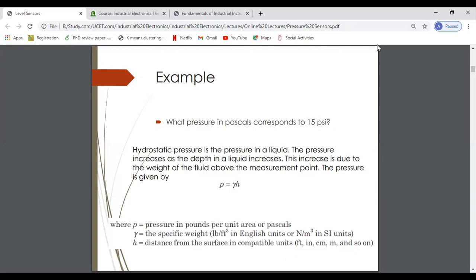As we have seen, it is not a very convenient unit and is often used in conjunction with the SI standard prefixes, for example kilopascals or megapascals, and you will see it in combination with Newton per centimeter square. But use of these combinations should be avoided in favor of Pascal with the appropriate prefix.